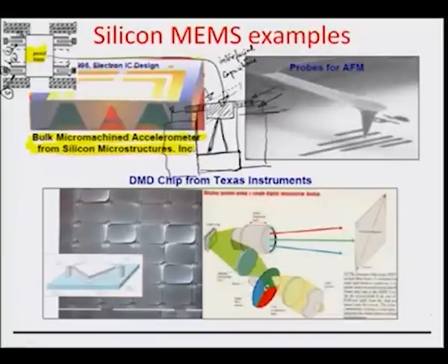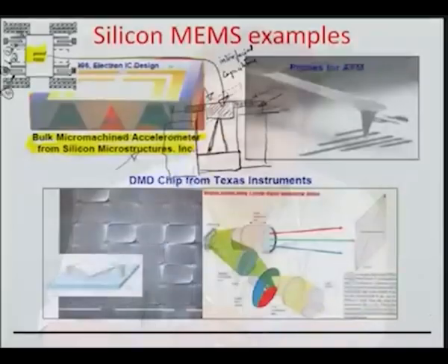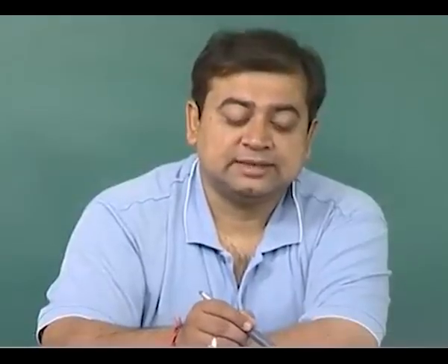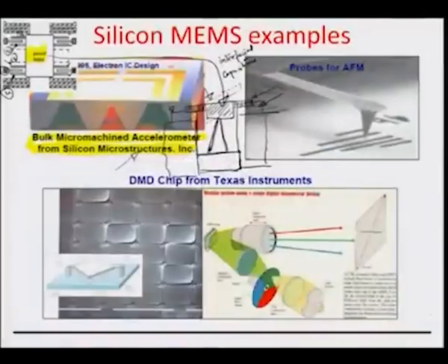So, if I can really calibrate this capacitance change with respect to the acceleration, roll, pitch, yaw, different physical parameters, that is really what an accelerometer measures. These accelerometers are increasingly used nowadays in the automobile sector for airbag based actuation, and in fact very small accelerations or decelerations can be recorded very easily using some of these structures.